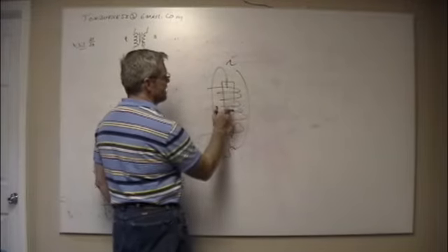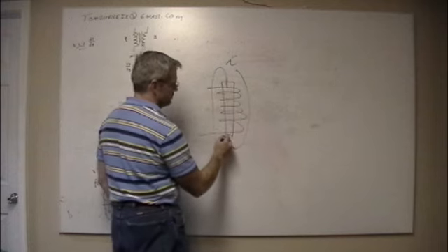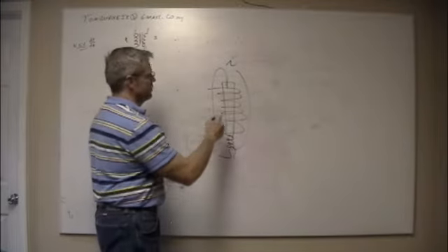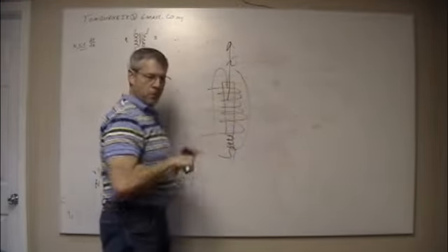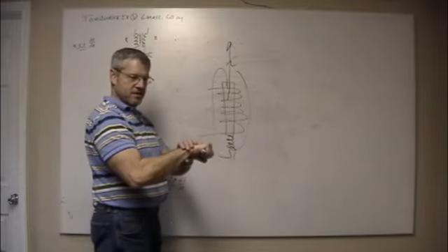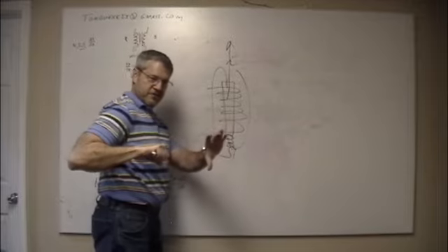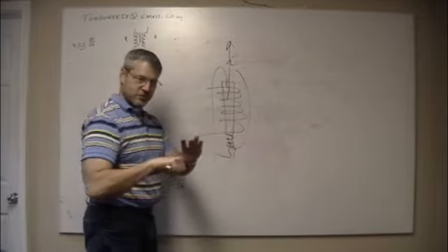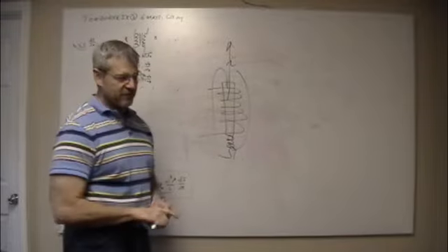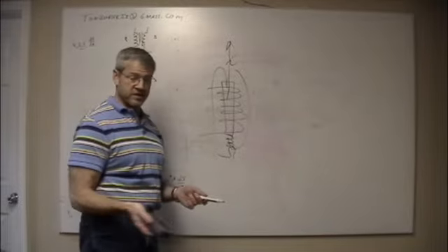But as it grows out, it's going to cause a motion. There's a couple different ways you'll do this. You'll see a spring on them. As current flows one way, it'll tend to push the bar out, and then as it turns off, the spring will pull it back. Or you can run current one way and it'll push it out, and run it the other way and it'll push it out in the other direction. So you can make a linear motor out of one of these. They generate a lot of heat. It's not the best way to do it, but they're useful for a lot of things, for small things.